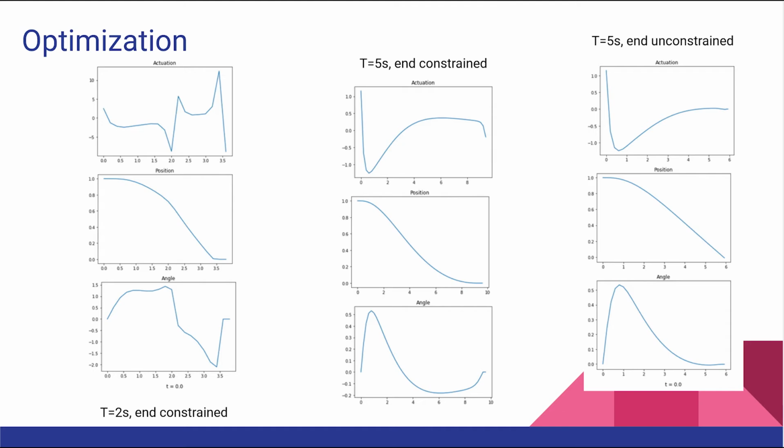In order to best compare trajectory optimization to LQR, we had to incorporate the same cost function and limit the number of constraints we put on the program. Once we did this, we noticed that given the same initial state, the trajectory optimizer would make some strange decisions about the Ballbot's behavior, sometimes skyrocketing actuation, even though this was being penalized. Eventually, we realized that this was due to the time constraint.